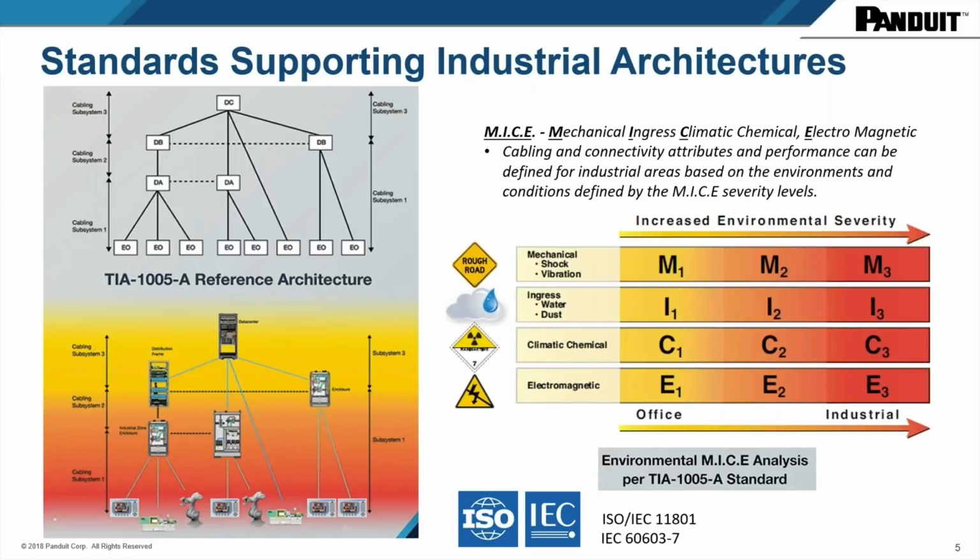If you go to a robotic cell, for instance, there's a constant flexing that takes place at the mechanical device. So the cabling that's connected between an edge sensor on the robotic arm to its base, that cable connection point is taking a lot of abuse over time. And that changes the environmental severity that needs to be applied in that instance.